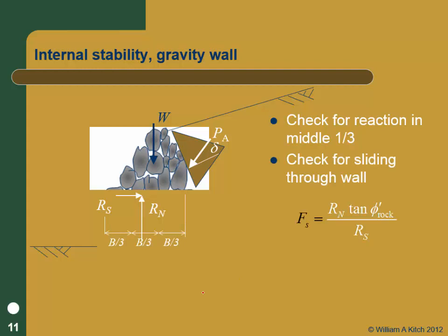In that case, we're going to find out whatever the friction angle is for a rock, and that could be a really high friction angle, particularly if it's all interlocked. We could have a friction angle greater than 45 degrees, easy. So it could be a really high friction angle, but we want to check that it can't. This is our structural failure of the wall. If you want to think about it, it's that wall shearing apart.